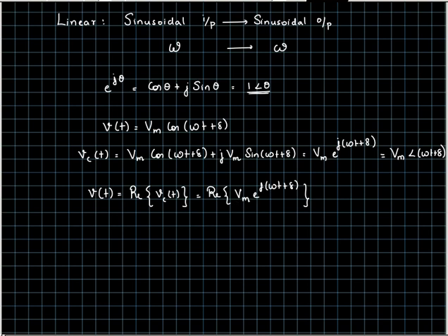That is done by representing v(t) as a complex exponential function, and then you apply this complex exponential signal to the differential equation. Now it is easier to solve, and you take the real part of the solution, and that will give you the desired output which would appear if v(t) is applied to the circuit.